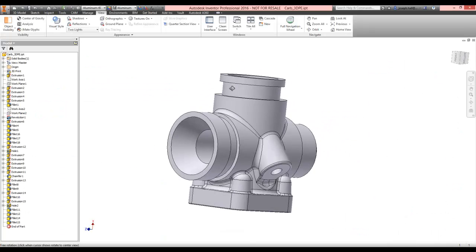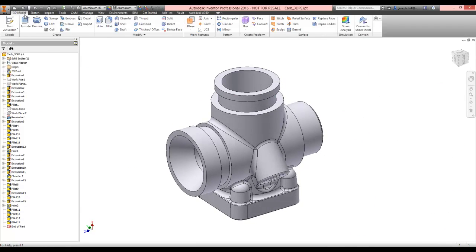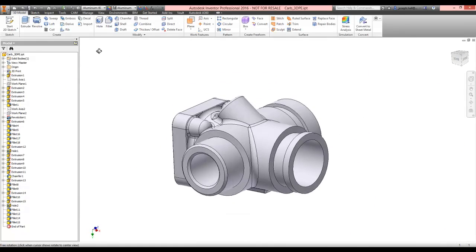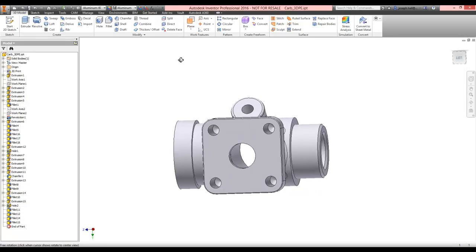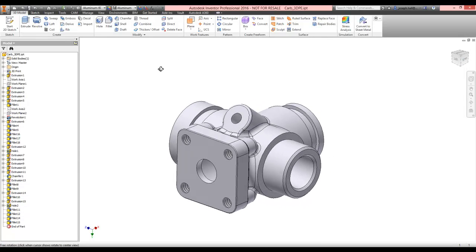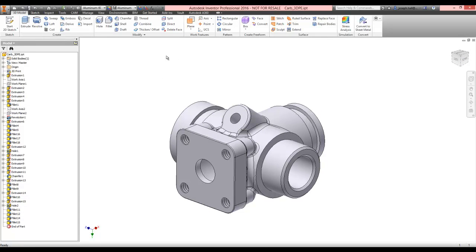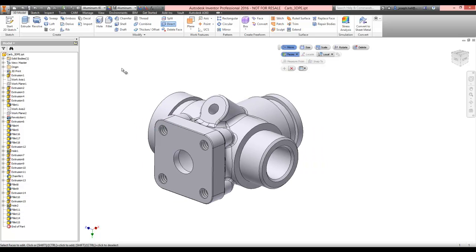So we nip into the software. I wanted to show you this first and foremost on an Inventor part, because we're going to spend most of our time working on geometry that's not native Inventor. The direct editing tool in 2016 sits just about here in the model browser. When you click on it, there isn't a formal menu for it. With some of the other tools, like extrusion, if I had a 2D sketch, it would give me a separate dialog box as well as the little floating menus, but direct editing just has the floating menus.